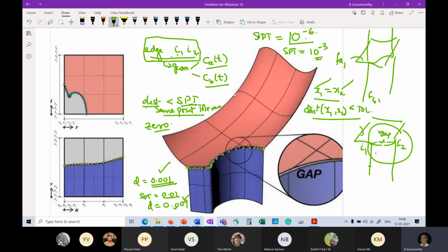If you are computing it on this surface, you use this expression. If you are computing it on this surface, you use that expression. And so that is not a very acceptable or a desirable solution. So that remains a sort of a problem situation for CAD systems. But with a combination of this approach and definition of a tolerance, right? People seem to be managing, except when they ship CAD systems from one system to the other. And if there is a mismatch between these two in the CAD systems, then we have a problem. Right? Okay. So that's pretty much what we wanted to talk about, representation of solids, right?